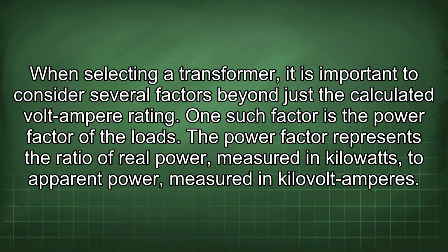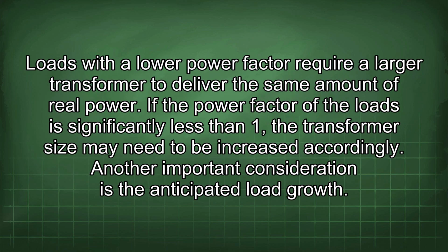One such factor is the power factor of the loads. The power factor represents the ratio of real power, measured in kilowatts, to apparent power, measured in kilovolt-amperes. Loads with a lower power factor require a larger transformer to deliver the same amount of real power. If the power factor of the loads is significantly less than 1, the transformer size may need to be increased accordingly. Another important consideration is the anticipated load growth.